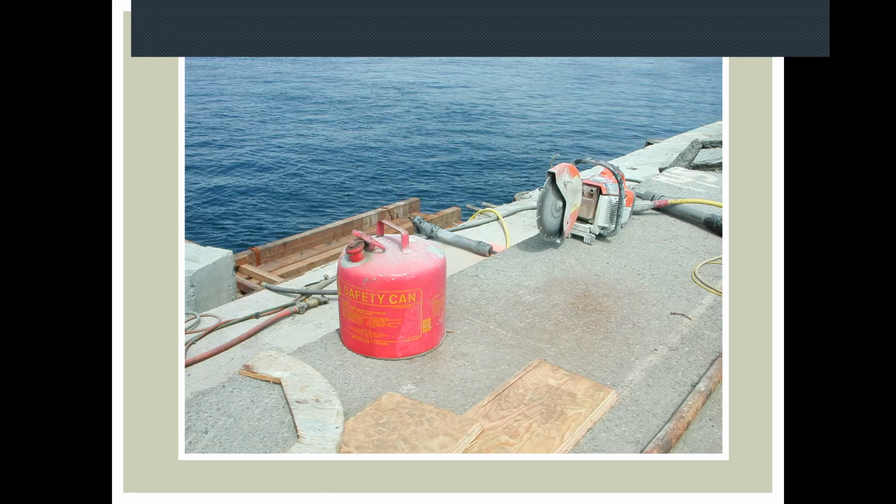Safety cans, which are safe, they tip over, they don't necessarily leak. They're not supposed to leak. But if they tip over and go in the bay, that's really not a good thing. So have the contractor, have the laborers manage their gasoline a little better than they have on this one. Put it in secondary containment, keep it off the dock, keep it away from the water.